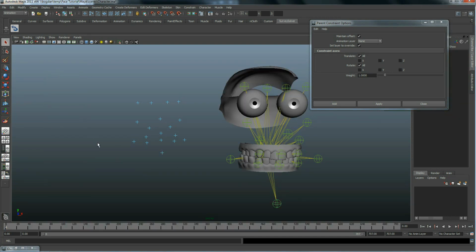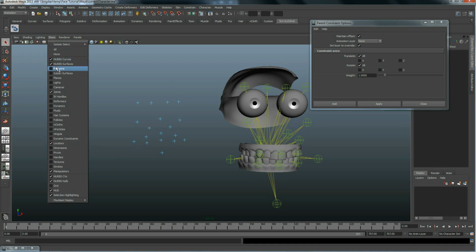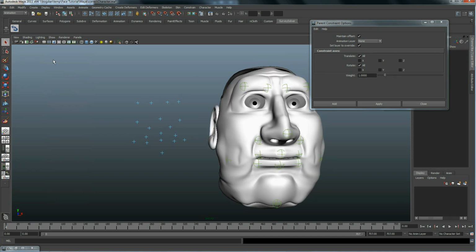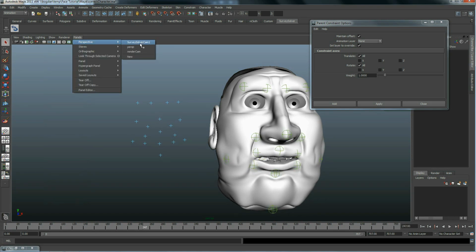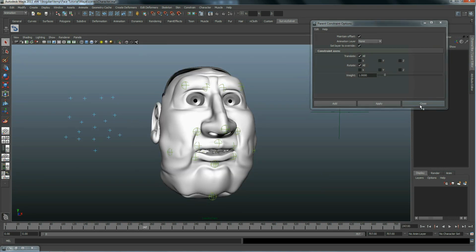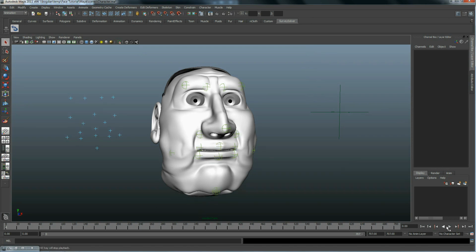When done, click play and verify that the bones are moving in a correct fashion. Make sure to set the playback to real time at 30 frames per second when reviewing. This can be changed after import by opening the animation preferences. Remember to select Keep Keys at current frames if you decide to update the frame rate.